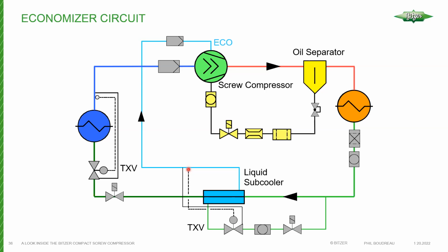So in this case, that's a fairly high superheat, and there's no problem having a high superheat going into the economizer port. In fact, that compressor could run without the economizer altogether. But the idea is when you have a high superheat here, higher superheat generally brings a little more stability. We don't want that valve bouncing around and hunting, because we're going to have a problem over here in the evaporator with its expansion valve, inducing hunting at that point. But also, if the superheats are too low, we tend to over-dilute the oil, and it reduces the lubrication value of the lubricant, specifically by reducing its viscosity.